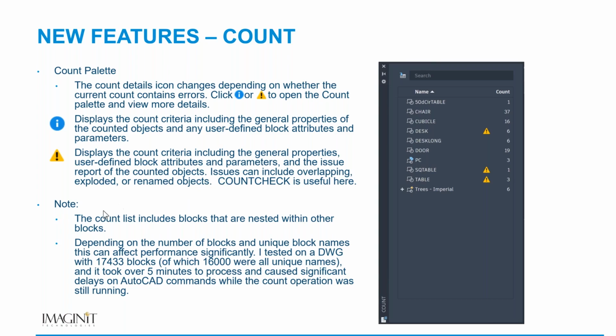So 2 things to note. The count list will include blocks that are nested within other blocks. That's very important to know. And then the other note here is depending on the number of blocks and unique block names in a drawing, this can affect the performance significantly.